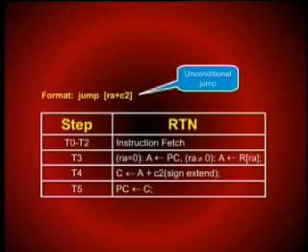register relative jump. In timing step T4, we add the constant C2 with appropriate sign extension to the contents of register A using the ALSU unit, and as a result, at the output, we would have in buffer register C the effective address to which we need to jump. In T5, we take the contents of C and load it to the program counter PC, which would just give us the position to which we need to jump through execution of this particular instruction.